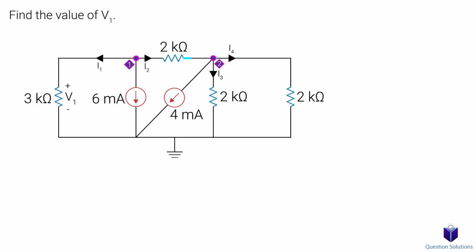This is just a guess, but what we are saying by showing a current flow from left to right is that the voltage of this node is at a higher potential than this node. We need to keep this in mind when we write our equations. Now we can label the rest of the resistor voltages along with the positives and negatives based on our assumed current directions. Next, we can label the node voltages. Since the numbers are taken, we will label them VA and VB.